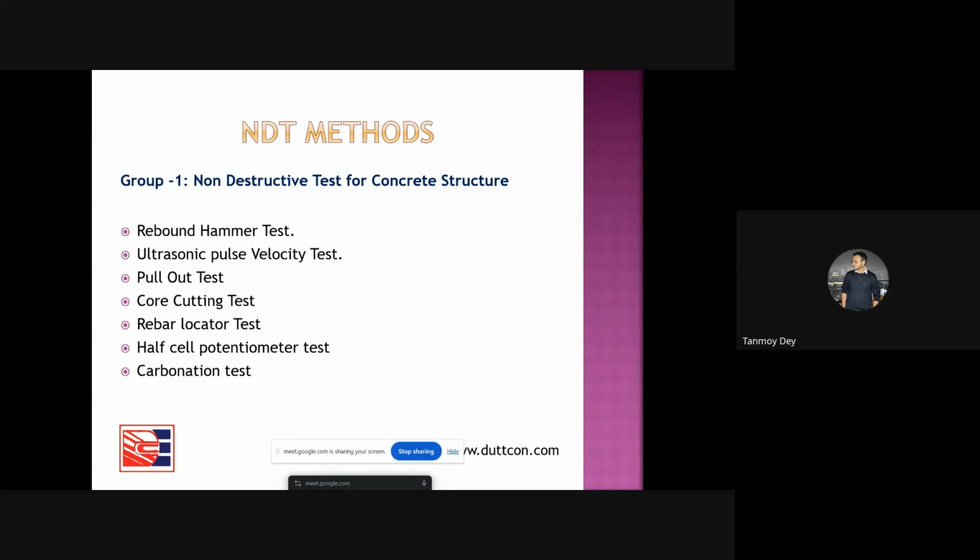What is a probe? In the probe, we have a piezoelectric crystal. When electricity is passed, an EMF is given, and this piezoelectric crystal vibrates. The frequency of vibration matches the frequency of sound. That's why we use a piezoelectric crystal within this probe. Sometimes this probe is called a scanner or a transducer. So many names are there: probe, transducer, or scanner.